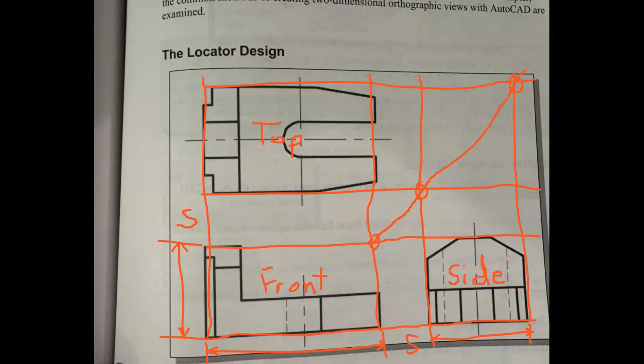I want you to do that because it's a safety check. Lots of times students mess up on their spacing or their depth when they're offsetting the lines. If you click here and create a 45-degree line, as opposed to using your object snaps, that's a double check that you've got the spacing in your 9 lines taken care of.